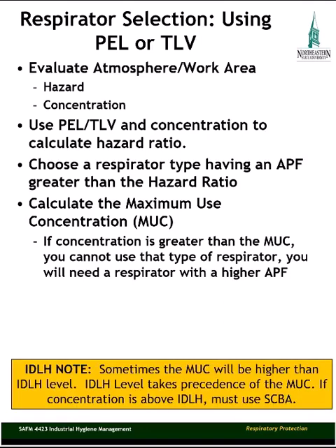And here's that note about IDLH that I mentioned in the previous slide. Sometimes the MUC will be higher than the IDLH level. The IDLH level takes precedence over the MUC. If the concentration is above IDLH, you must use an SCBA, a self-contained breathing apparatus.